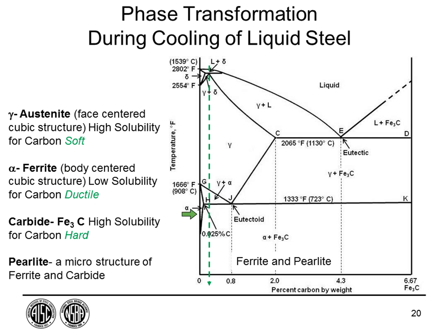And then when it goes below that, we still have the ferrite, but we'll form something else, a carbide, sometimes called the cementite phase, which is very hard. We have a peculiar microstructure that's formed at this lower temperature. It's called pearlite, and that's a lamellar structure of the ferrite and carbide that's formed from the gamma phase that has the eutectoid composition. And so that will determine this amount of pearlite.